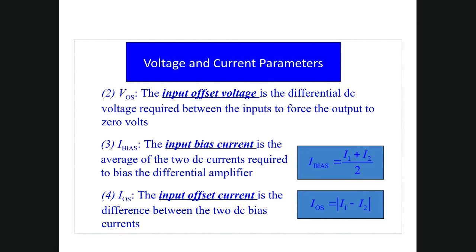If you understand the behavior of a weighing machine well, it will be clearer that input offset voltage is a voltage that we apply at the input of the OPAMP, and the purpose is to make the output of the OPAMP 0. This is a precondition needed to make sure that once your output is 0, after that, if you apply your input signal, you get a perfect output. Okay. Anyway, we will go through this in detail so that you will find it more understandable. For right now, that is all we can say for this point.